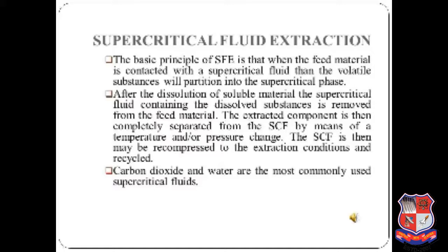After the dissolution of the soluble material, the supercritical fluid containing the dissolved substance is removed from the feed material. The extracted component is then completely separated from the supercritical fluid by means of temperature or pressure change. The supercritical fluid may then be recompressed to the extraction condition and recycled.